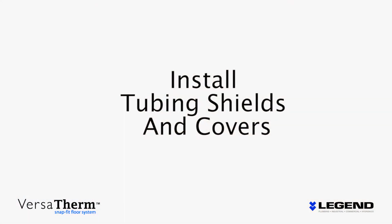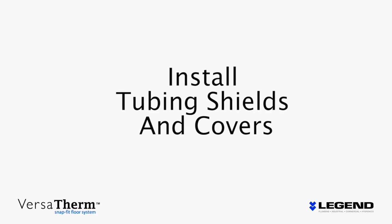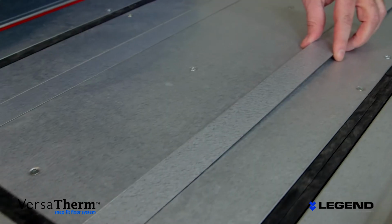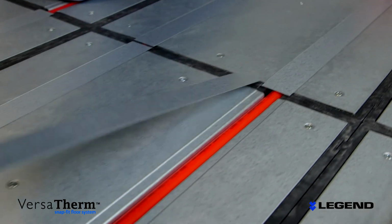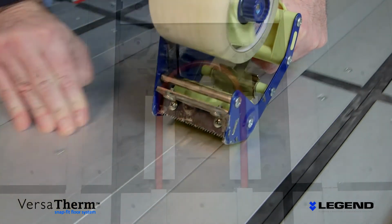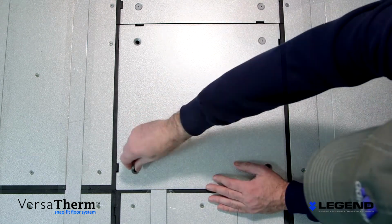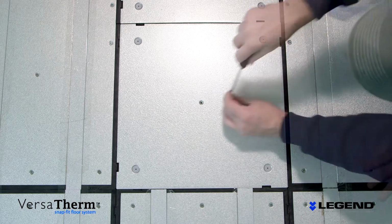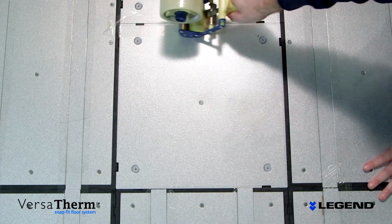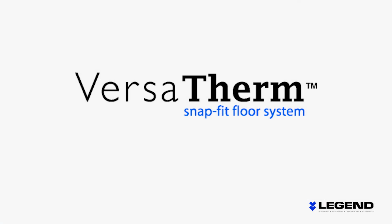The final step is to cover all of the tubing. This protects the radiant tubing and maximizes the efficiency of the VersaTherm system. Start by laying the tubing shields over the tube channels on the main panels. Tape them down using 2-inch packing tape. Install the return panel covers by pushing the 4 clips into place and securing the center with a single screw. Finally, tape down the edges of the return panel covers. All hardware for securing the return panel covers is included. That's all there is to it.